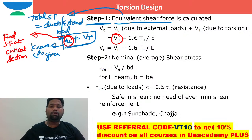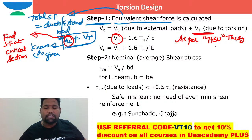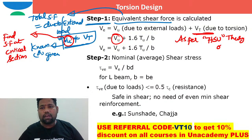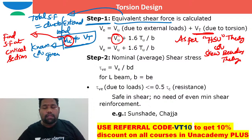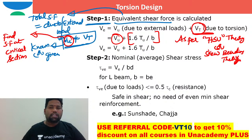So Vu. And coming to Vt, what is the shear force because of torsion as per Hsu theory? HSU is the name of the scientist. As per Hsu theory, or another way, this person proposed the skew bending theory. As per skew bending theory, the shear force that comes into picture because of torsion is 1.6 times the torsional moment Tu divided by b.